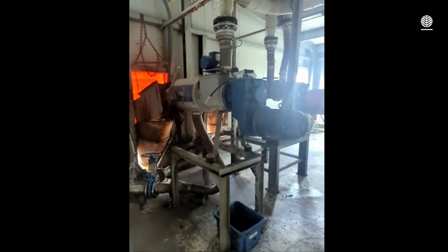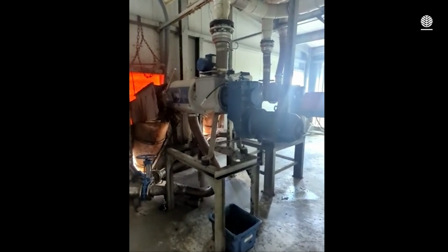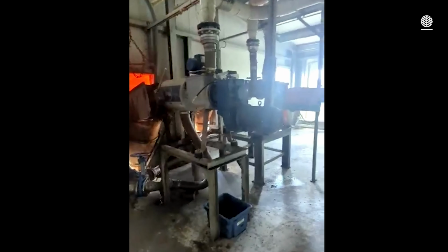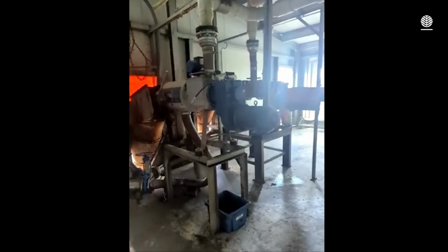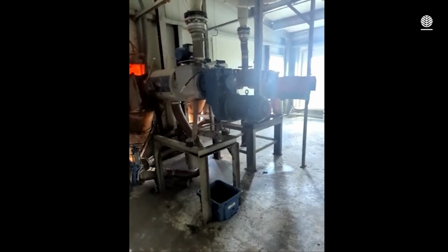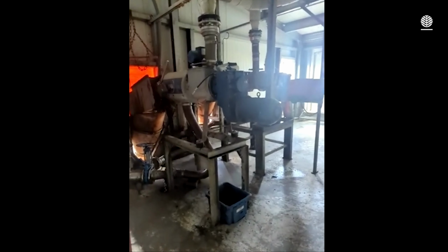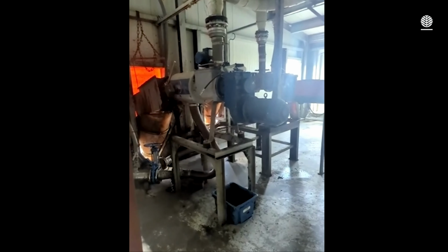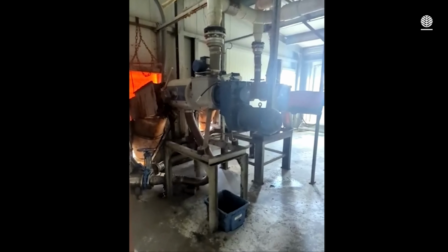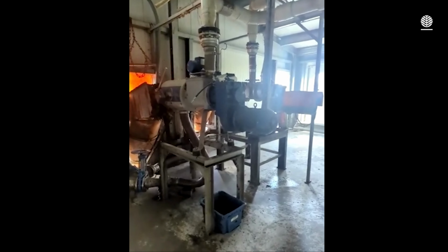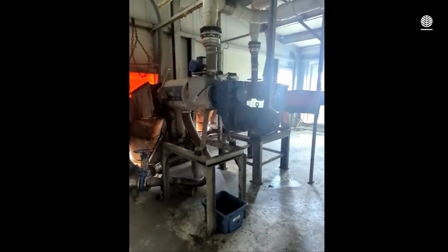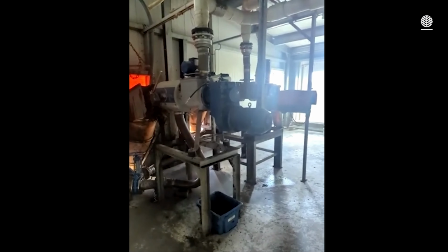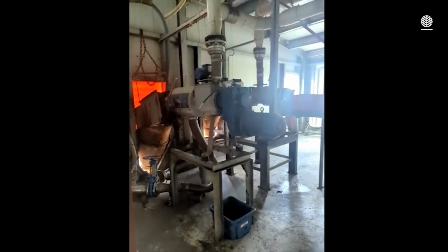So it's a screw press. It's a little bit tricky to install because the content from the digester is producing biogas in the digester, and it produces biogas in the pipes as well. And it produces biogas in the liquid after dewatering as well. So you have to avoid gas bubbles inside the pipes and the pumps. So you have to get rid of them.